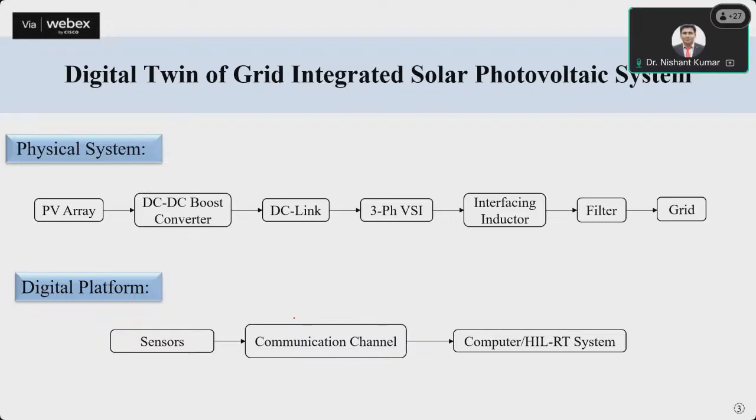Okay, so this one is related to the basics of your digital twin. Next, what I'm going to discuss here in detail is a setup of digital twin for the converter side. So in this converter system, I'm going to use the source as a solar PV, right? And on the output side I have attached one grid, and then on the PCC of the grid we can attach our EV. So we can say that this is an AC charger, or you can attach on the DC link. So you can say DC fast charger, whatever terminology you want to use. So if you attach your charger here, you will call it an AC charger, and here you will attach the DC charger. But those are just like a load.